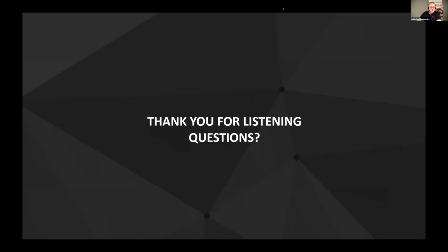Question: are the out-of-box depths fairly accurate without adjusting according to the hyperbola? I guess what the software provides as a starting point, and I would say no, or possibly it would depend on your data set. Sometimes it will match, but this is a general value that we add as a starting point, and then you have to make either a hyperbola fitting or a migration to get to the right velocity of your profile and your data. Or choose one of the preset velocities.